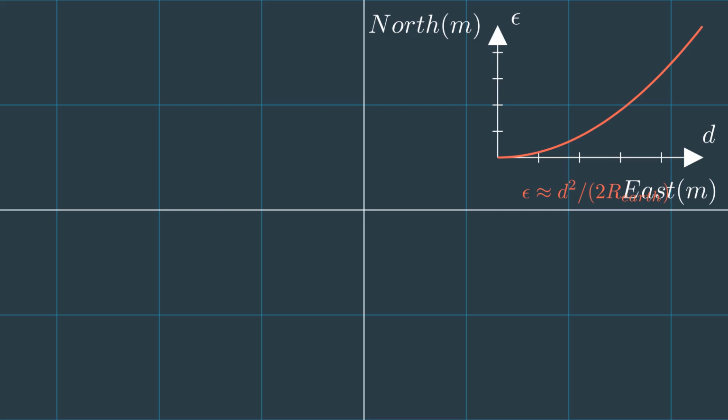But the key thing is that the error grows significantly as you get further away from that center point V. How does it grow? Linearly? No, it's worse than linear. The error is approximately proportional to the square of the distance, d, from the center point. The formula is roughly E ≈ d² / (2R), where R is the Earth's radius. Okay, so double the distance, 4 times the error, triple the distance, 9 times the error. That could get bad quickly on a long street.